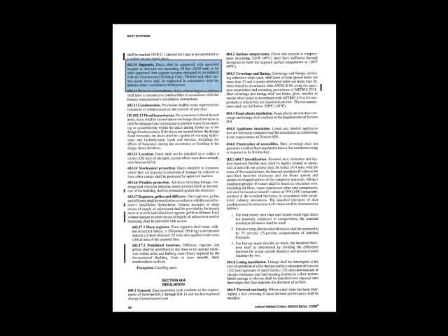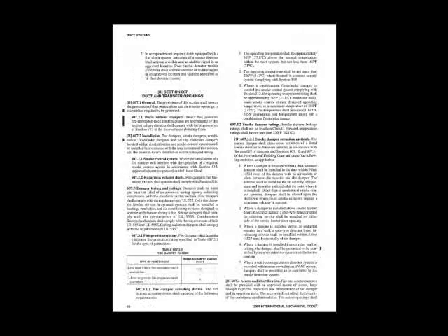Section 604 talks about the insulation that can be used in ducts. Section 604 is concerned about energy efficiency as well as smoke, fire, and flame retardants. That's the purpose for 604.3. It talks about vapor retardants, because we don't want mold and mildew building up in ductwork. Section 605 talks about air filters. Section 606 talks about smoke detection systems and control. We want to make sure that we detect any smoke in ductwork and then shut all our systems down. We do not want to be moving smoke around ductwork.